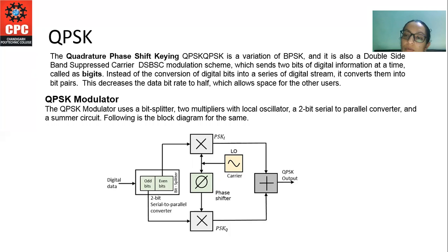There are 4 output phases, so there must be 4 different input conditions, because the digital input to a QPSK modulator is a binary signal, base 2, to produce 4 different input combinations. The modulator requires more than a single input bit to determine the output condition.